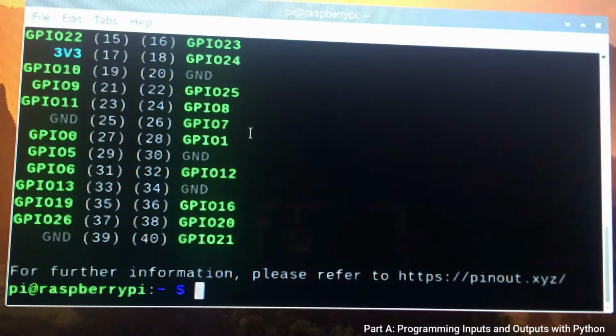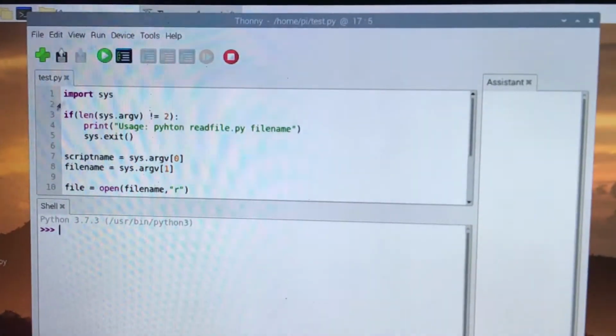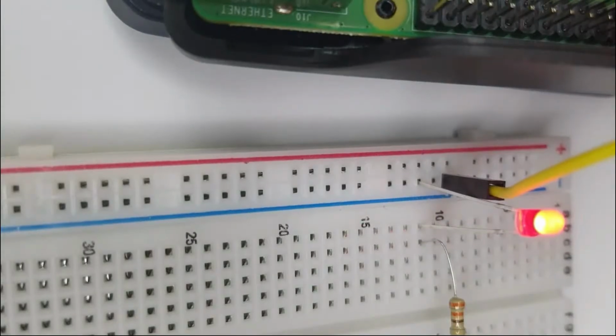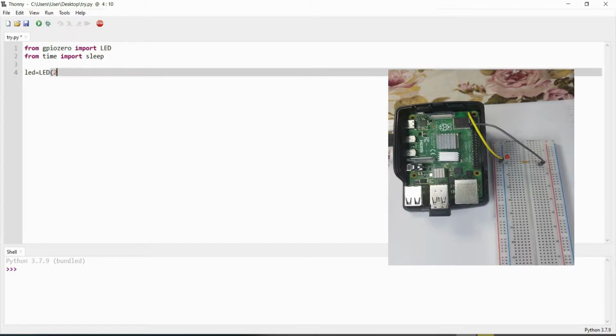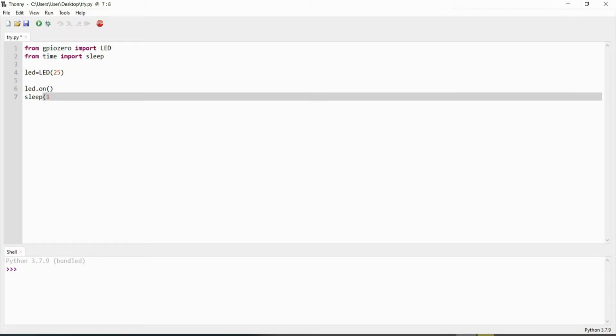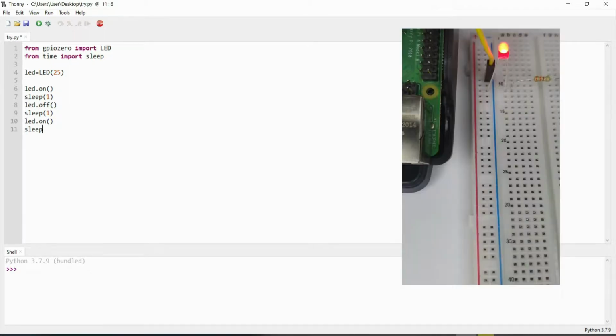Open the terminal window and write out the commands to show the GPIO pins. Then open the Python editor in your Pi and at the same time test the red LED with the 3.3V GPIO. Connect the LED with a resistor to ground and pin 7. Set a coding on Python to make the LED blink for every 0.5 seconds and execute it.